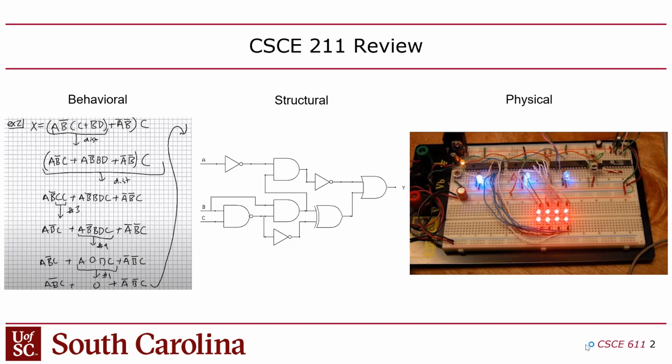And then finally, in 211, you should have then learned how to take a digital logic schematic like that one, and then for each one of the gates associate them with a slot on one of these TTL 7400 series logic chips, and then connect them together on a breadboard through their pins with wires, where each one of the wires on the breadboard matches up to one of the wires in the schematic, right?